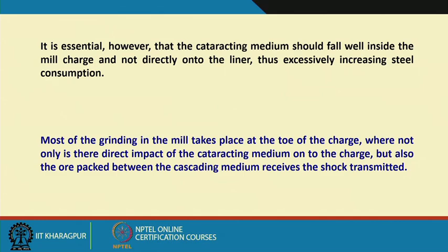That is the design engineer's role: how do I design my mill so that my grinding media have a proper counteracting action and hit my material directly on the toe. Otherwise, it will be a wastage of energy, and it will unnecessarily aggravate the wearing process of my medium as well as my liners.